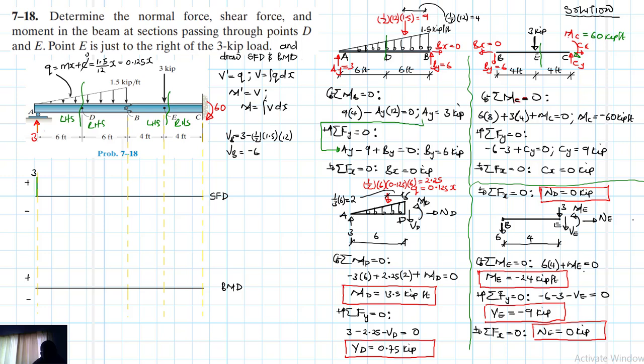Right. So from here we are going to move, like we said, the loading is negative and increasing. Therefore, the slope of our shear will also be negative and increasing. So negative and increasing will have a slope like this. Let's say this is your value of 6 here.